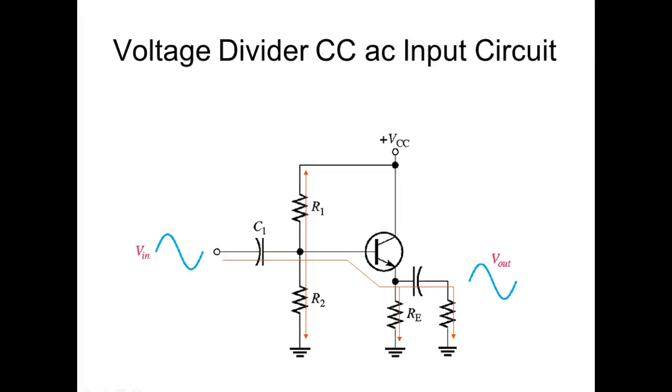We're going to ignore the capacitor because, if we choose it the right size, the reactance of the capacitor is not going to be enough to affect the circuit anyway. And it goes through RE. So the input impedance is a little harder to see, but we're not dealing with that in this class. But if I was going to calculate current gain, that's what I would have to do. If I was going to try to measure it, I would measure it right here.